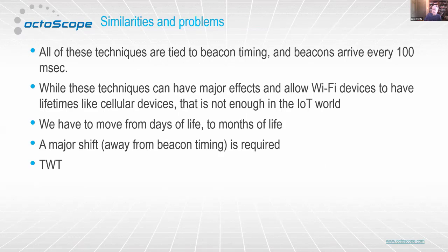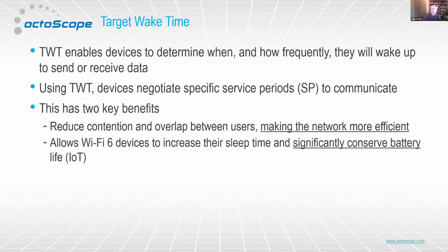And those beacons are arriving many times every second. So if you want the devices to support not just cellular-like lifetimes, but smoke alarm-like lifetimes, then you have to move away from days of life to months of life for a battery. And so you needed a big shift away from beacon timing. And that's what target wake time is all about.